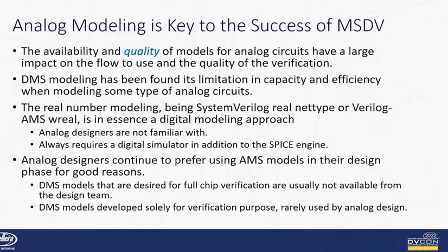So analog designers continue to prefer using AMS models in their design phase, for some good reasons. The DMS models that are preferred or desired for full chip verification are usually not available from the design team.